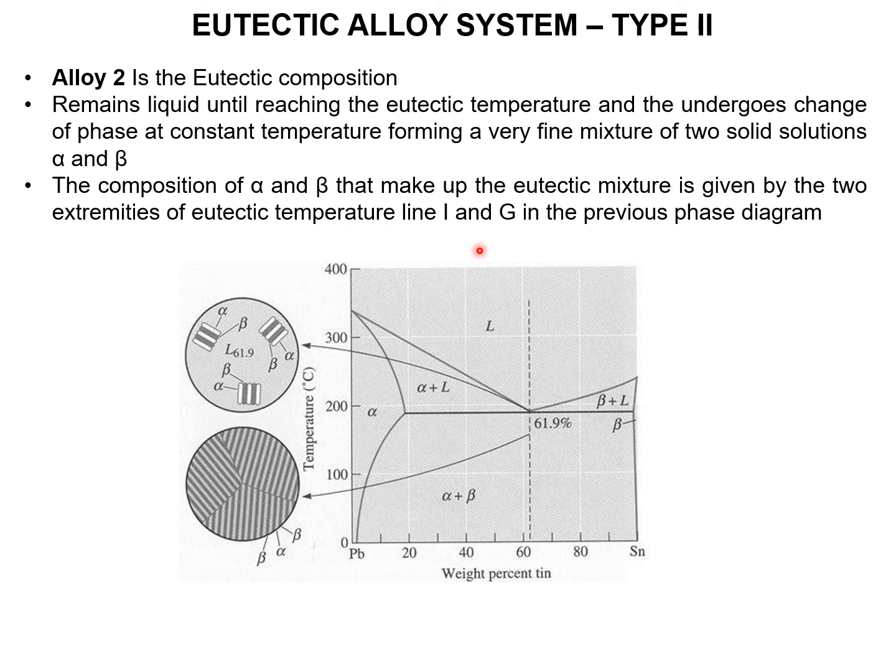Now we will see another alloy at 60 percent of B, 40 percent of A. This is alloy 2. Here it is entirely liquid. Before the eutectic reaction, it will be liquid solution plus small alpha grains plus beta grains. Both mixtures will be there. Once it crosses this eutectic line, the entire liquid is converted into a plate-like mixture. We call it a plate-like mixture. This we call a eutectic reaction.